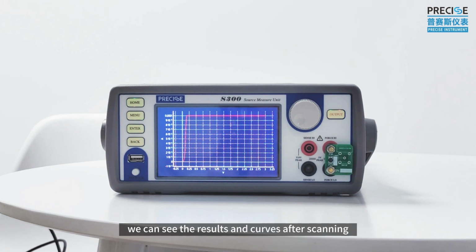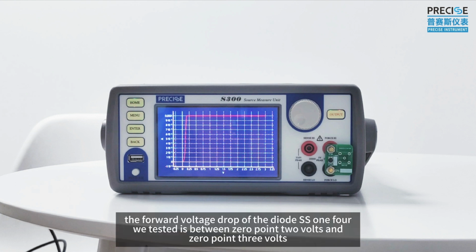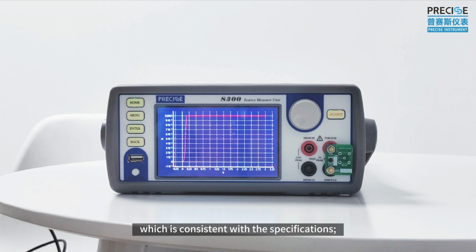We can see the results and curves after scanning. From the results we can see the forward voltage drop of the SS14 diode we tested is between 0.2 volts and 0.3 volts, which is consistent with the specifications.